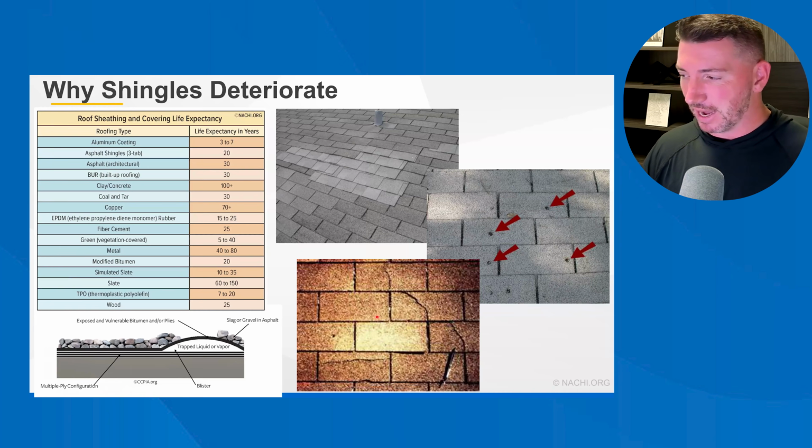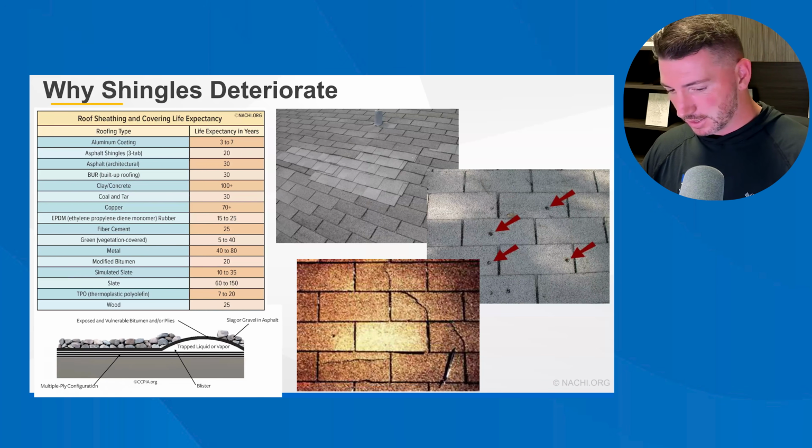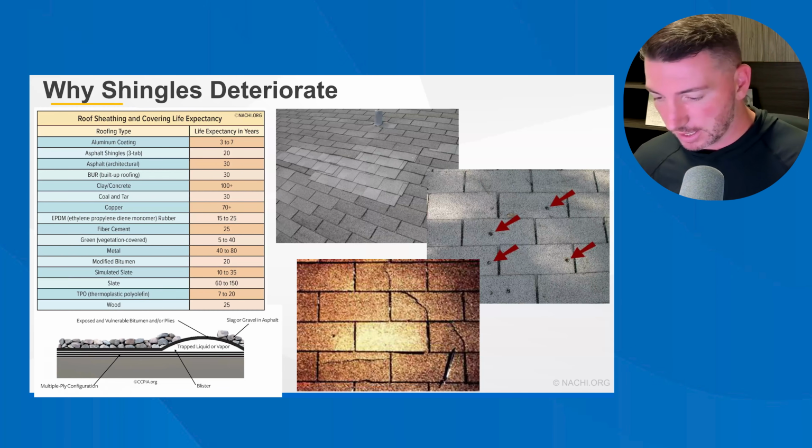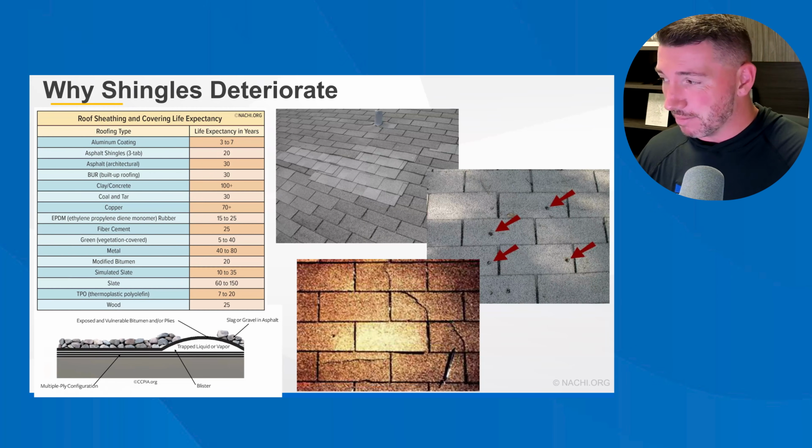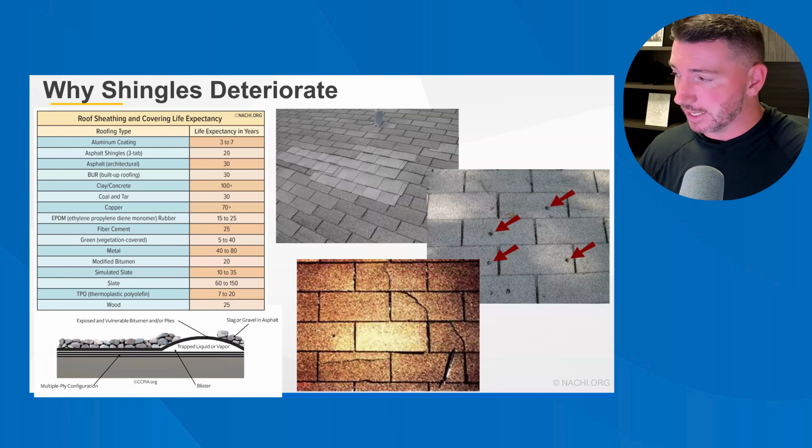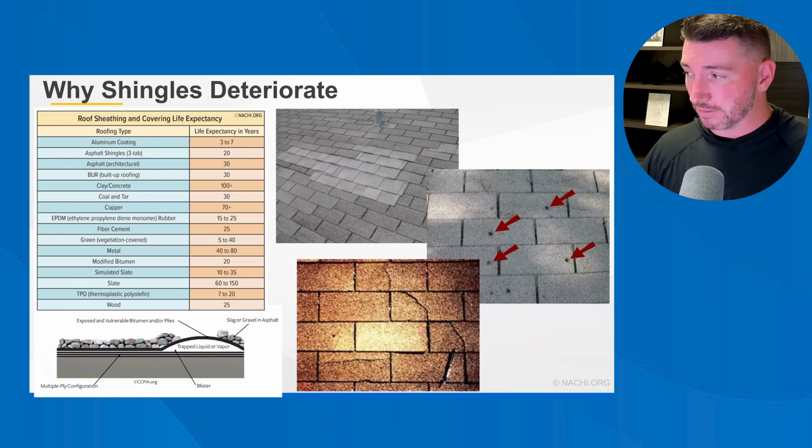It's really a manufacturing defect with the sealant strip. It's bonded too tightly to allow for movement when things are heating up. But it's something I would call out as a potential issue with the roof, but it's not really anyone's fault in particular. And then that middle one to me looks like fraudulent damage caused by a ball peen hammer. That is my guess based on the limited information I have in one picture, but as uniform as those impacts are, that's for sure not hail damage. So it's either a ball peen hammer or something else that is not hail related, but that's 100% not hail damage.